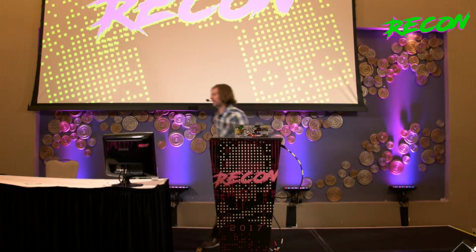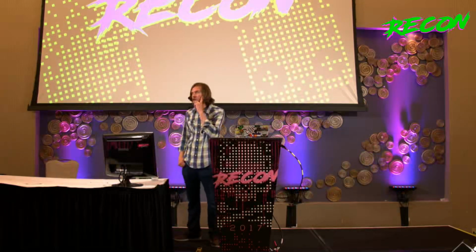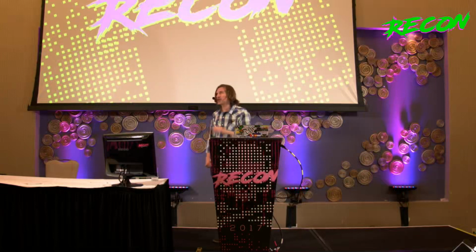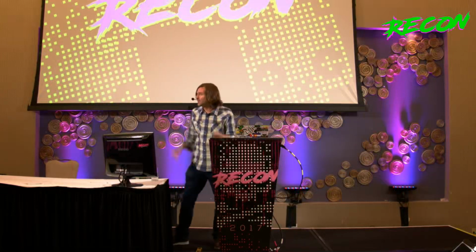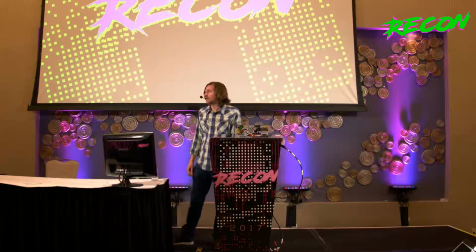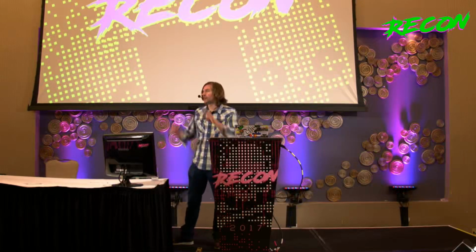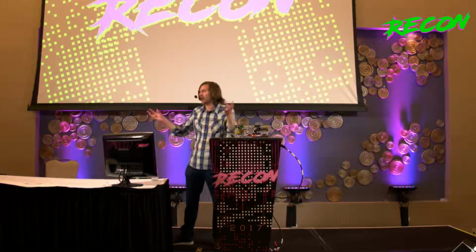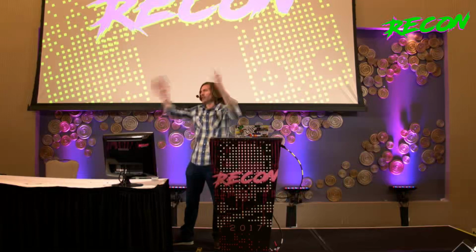So you might have some kind of a system where they're not inverse. If you had, let's say, a quaternary spreading sequence instead of a binary spreading sequence, I'm not sure I know a practical implementation of that, but in theory, you could have a spreading sequence that consists of multiple points around the unit circle in the complex plane, and they don't have to be two opposite points, but they probably should be equally spread around the unit circle.